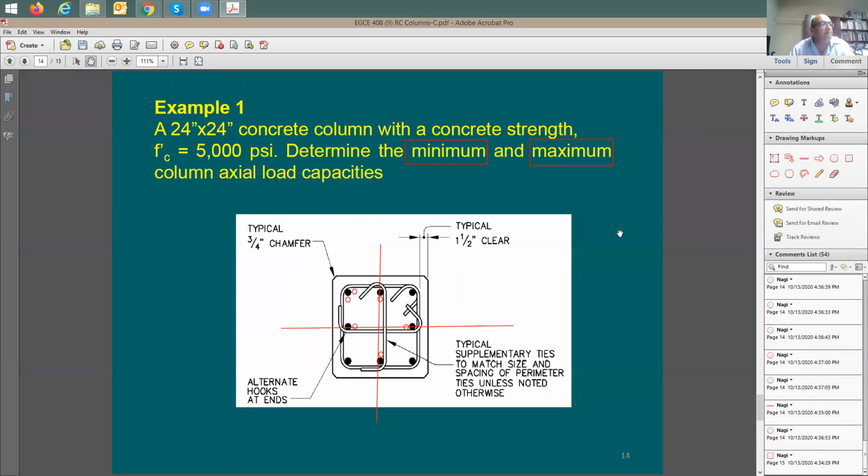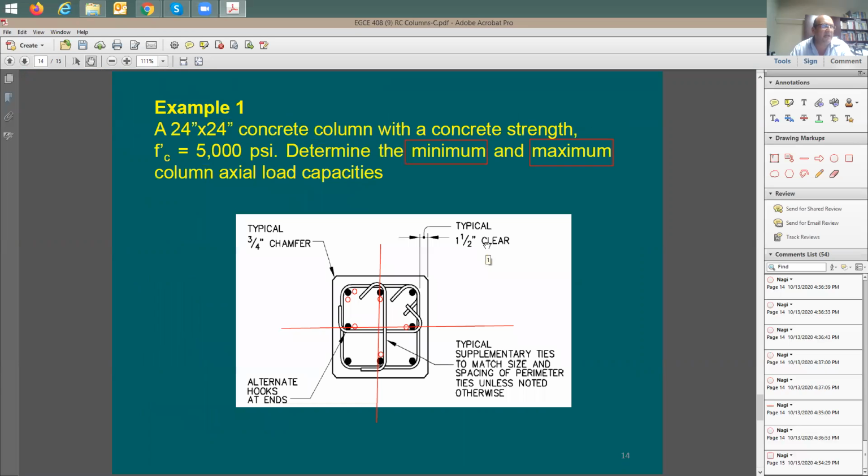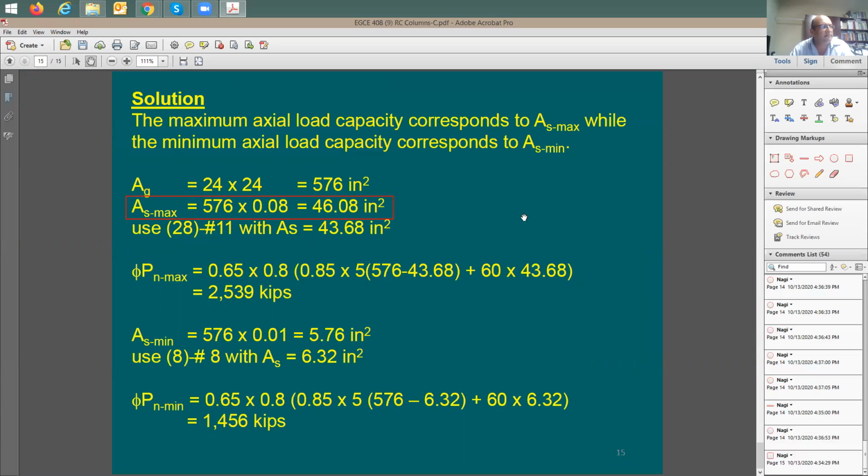So I said, okay, I'm going to go here to the largest rebar size, number 11 rebar. This is the largest rebar size that I can use. I'm going to use 28 here. There's a way to put 28 here, but it's going to be really congested. You're going to have just lots of rebar. Wouldn't it just be better to increase the rebar size?